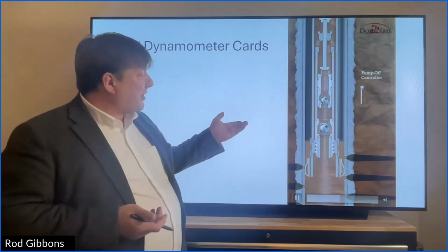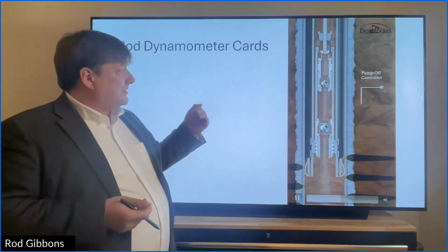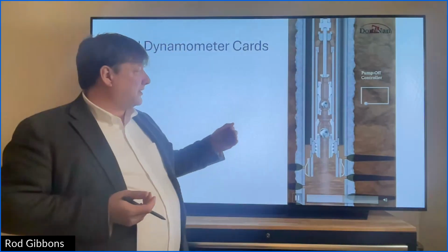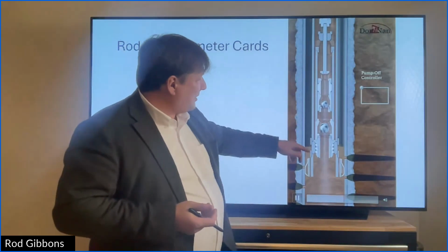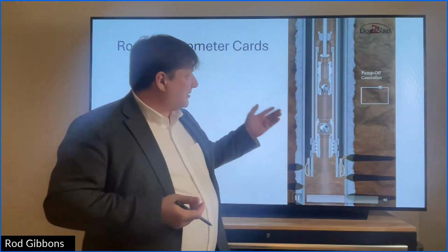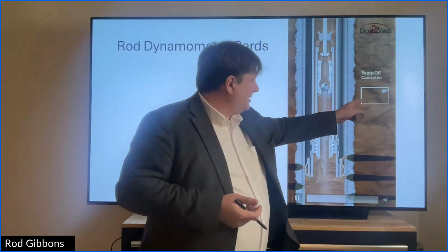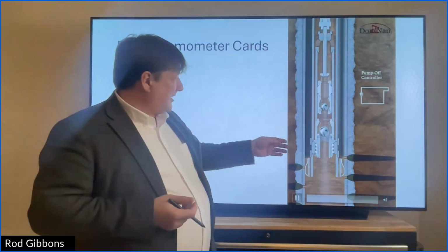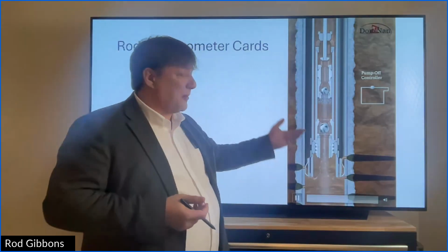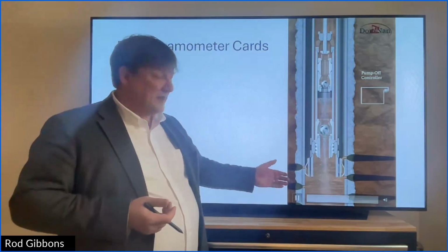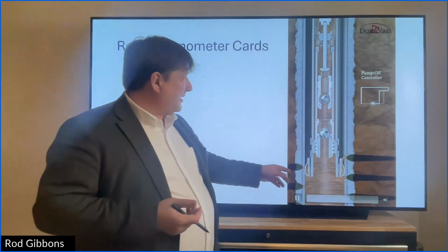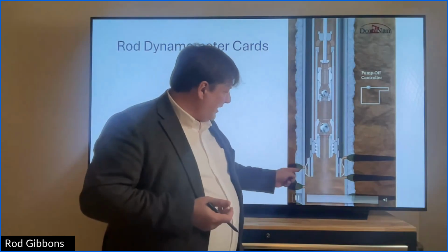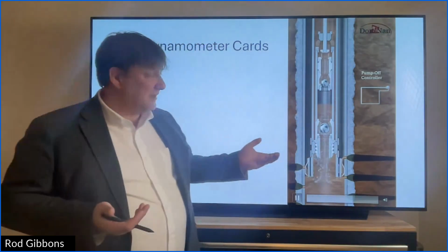And so a pump off controller is a piece of technology installed on pump jacks so that as you are pumping fluid here, you see you want to have a nice square pump card, but as you start getting, your pump is too big for your inflow. So what's happening is you're starting to get gas that's in the annulus come in, as well as the oil that's coming in, because the pump is too big.